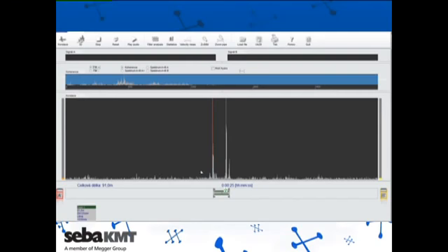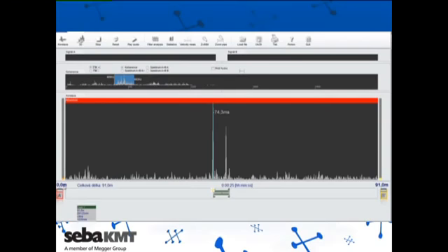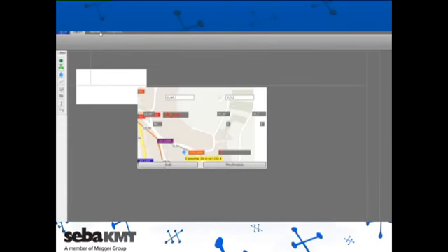Now, if we select a frequency filter in the region of 700 Hz, only the leak within the section measured is displayed, and that with an even better precision of 20.7 meters from the yellow transmitter. If we set the filter to the second low frequency maximum of the coherence curve, the leak location is displayed on the orange sensor, which is to be attributed to the second leaked noise outside the section measured. This was actually the influence of the second leak, which was located in this section of the network.